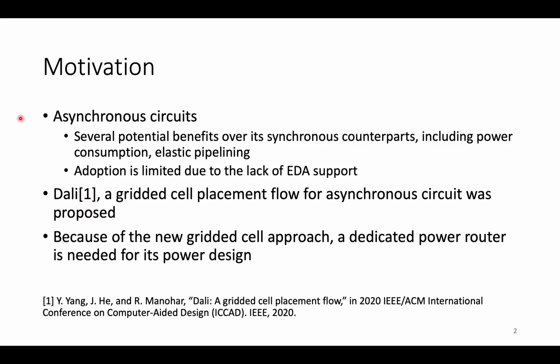First, motivation. Asynchronous circuits have been demonstrated with several potential benefits over their synchronous counterpart, including power consumption, elastic pipelining, etc. But their adoption is limited due to the lack of EDA support. So recently, Dali, a gridded cell placement flow, was proposed for asynchronous circuits. It used a new gridded cell approach, and because of this, a dedicated power router is needed for its power design.